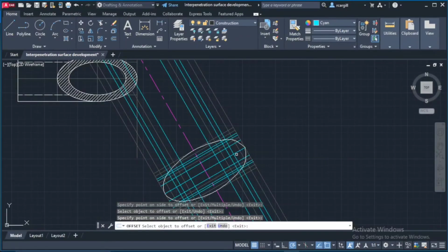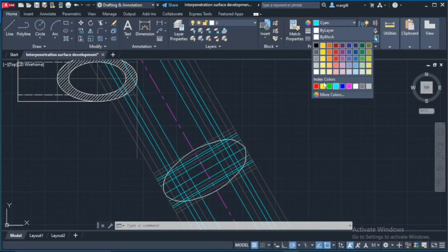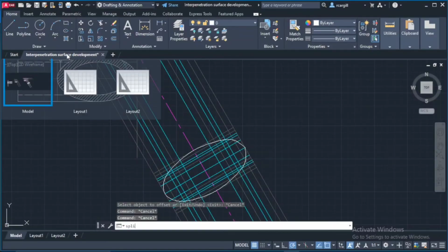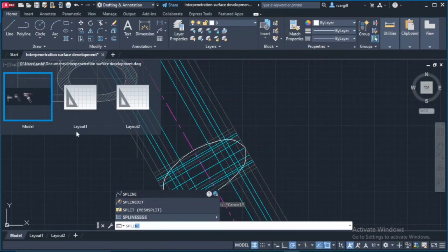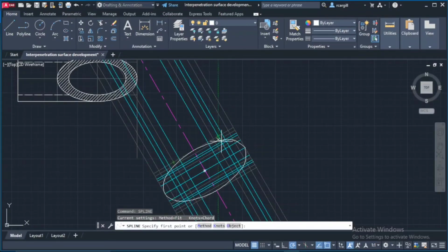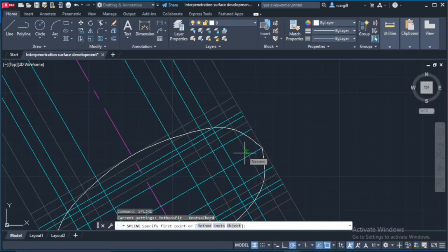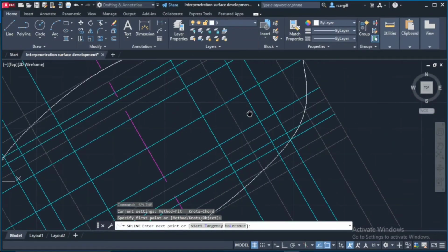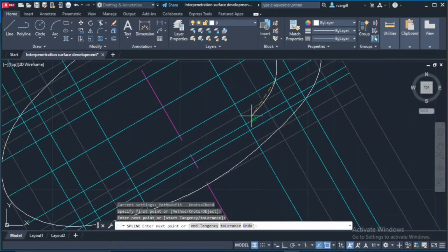So we're going to be matching some stuff here. What exactly are we matching? Let me go back to the 0 layer and change this to the bilayer. I'm going to select a spline once more. When I select the spline, I'm just going to be matching cyan lines. Where this center line right here, the cyan center line, meets this first perpendicular line here, that's our first point. Then we're going to make this our second point where the next two cyan lines meet.